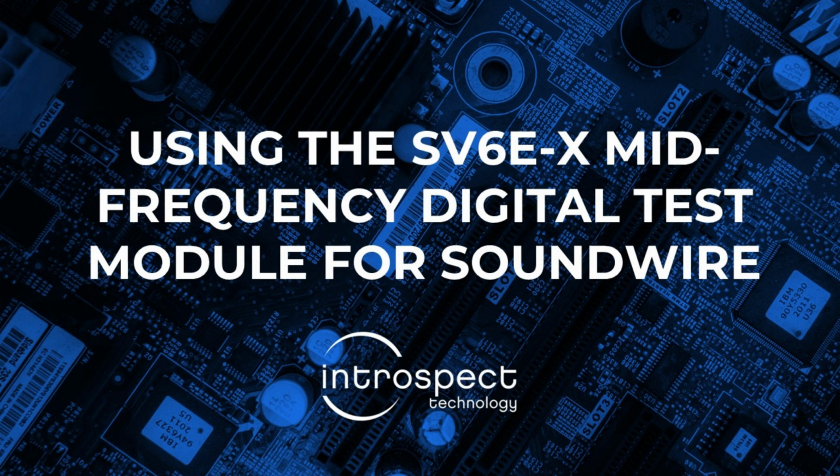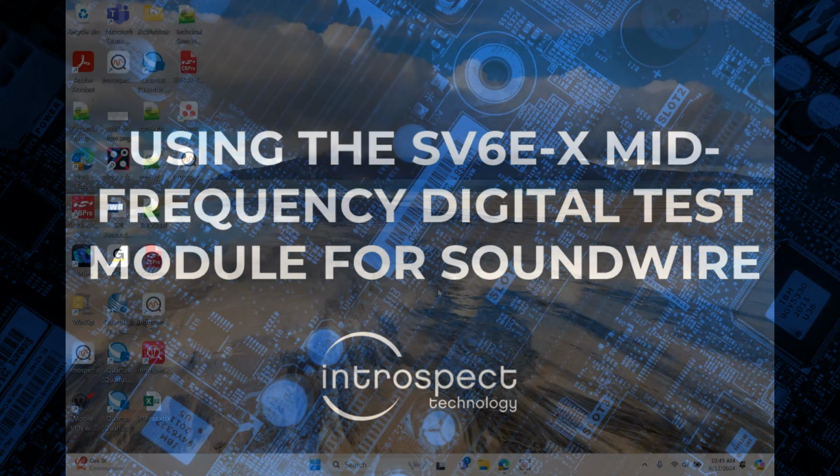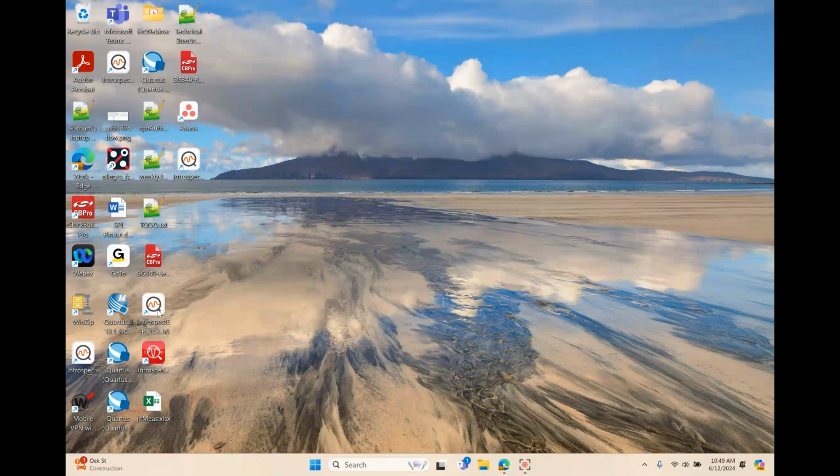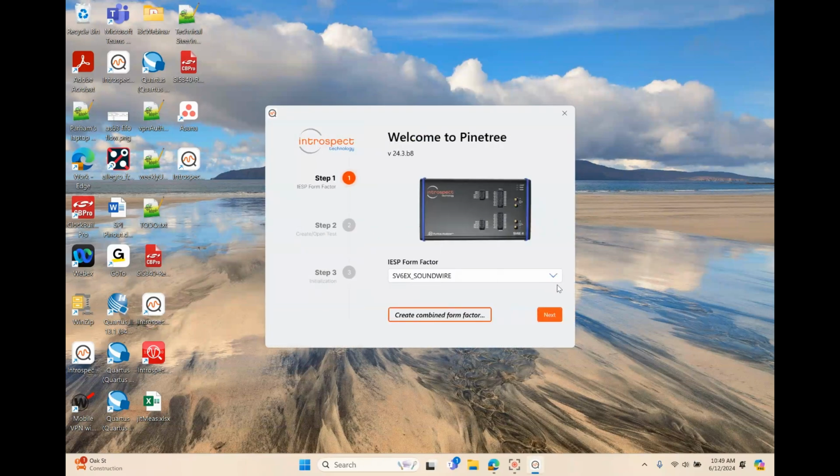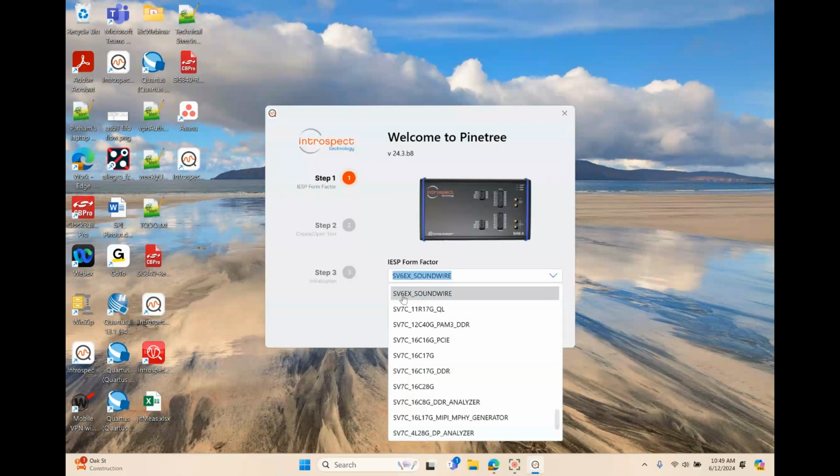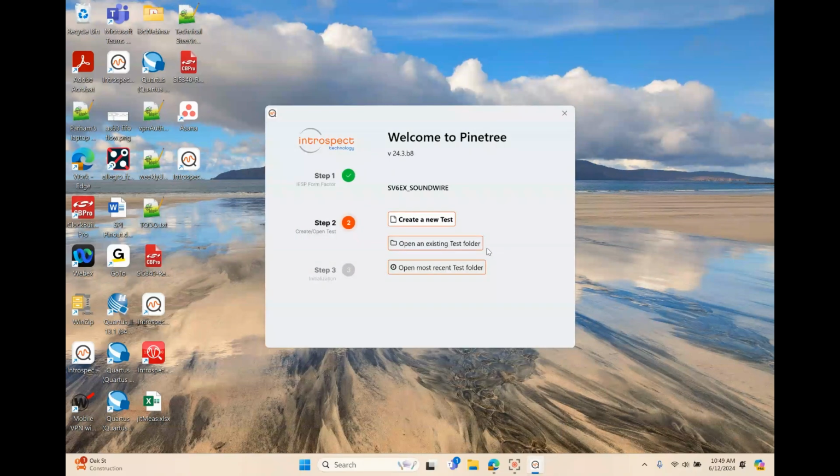In this video, I'm going to be introducing the basics of how to use our SoundWire test tool. So first, I'll start by opening the Pinetree software. Then, under the list of form factors, I'll select the SV6E-X SoundWire. In this demo, I'm going to preload an existing test, but you should be able to start a fresh new test if you want to.